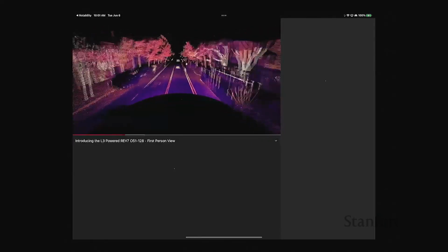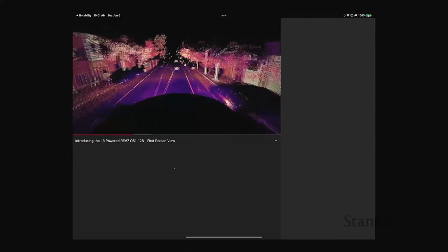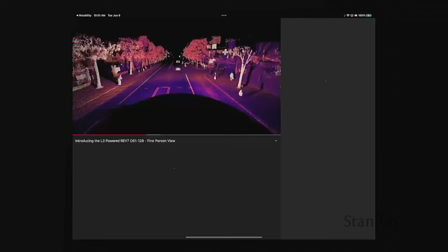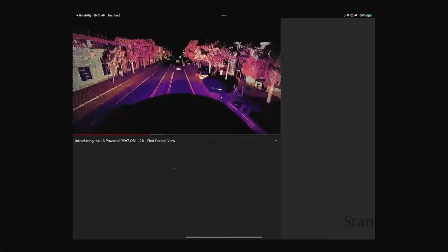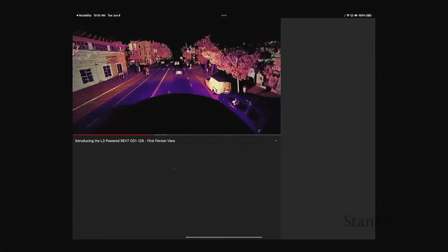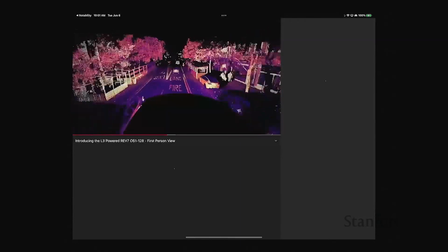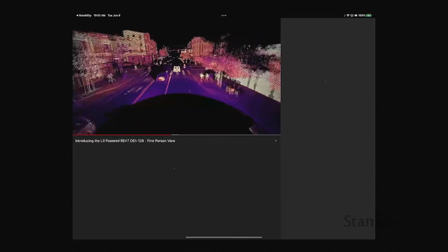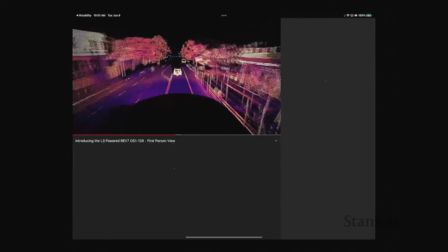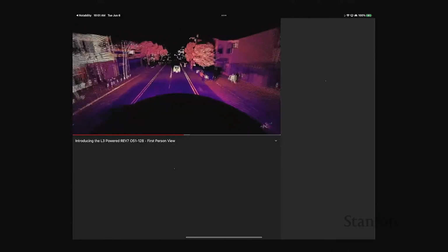So it's a direct detection LiDAR. There's no velocity, but they get excellent reflectivity. And basically the color here is reflectivity at IR wavelength. So they get very nice intensity or reflectivity out of this. Very dense. This is a spinning LiDAR with 128 scan lines, uniform in elevation. It sees up to, I think, 200 or 300 meters, excellent resolution, high frame rate, and so on and so forth. That's the state of the art today.